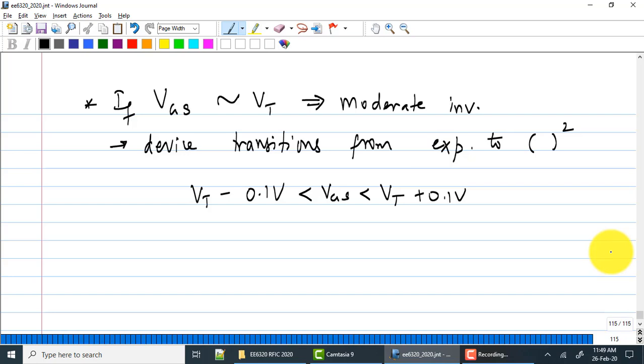You want very, very small, you want VGS minus VT to be almost zero. How do you force the overdrive voltage to be almost zero? Bias current small. And corresponding along with that, what do you do? But maybe the circuit is one where you need the bias current to be a milliamp, or 100 microamps. Maybe there is something else that is telling you how much current to burn.